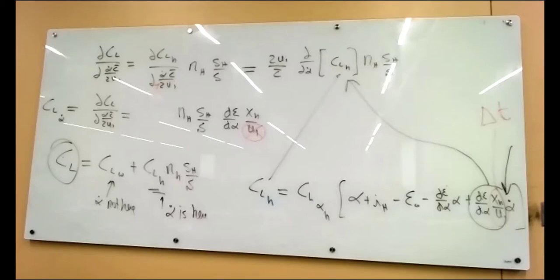That'd be a pain, wouldn't it? Okay, I want to do my analysis at 100 knots. Okay, recalculate CL alpha dot. Now I want to find it at 200 knots. Well, okay, recalculate CL alpha dot for every velocity.